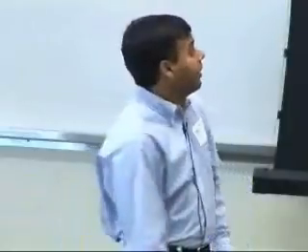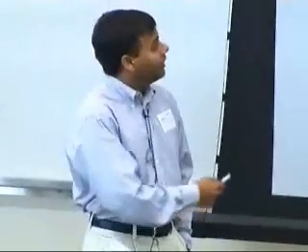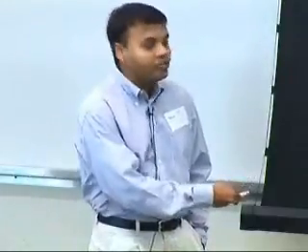Now, there are some constraints about doing online self-test. First of all, since we are talking about delay shifts, we are talking about very thorough delay tests. You cannot simply do some stuck-at fault testing and say, well, I'm done. You have to do pretty thorough delay tests to be able to find these problems. Number two is when you do online self-test, you cannot have any visible system level downtime, because if the system is down, that's of no use. There should be minimal application level performance impact. That means you have to be clever about how you schedule these online self-tests. Of course, it has to be low cost, and of course, it has to have minimal design flow impact.